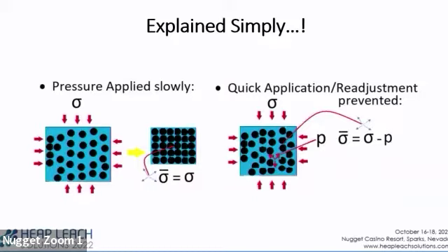The shear strength of a soil is the overburden effective stress, or the confining effective stress, times the tangent of the friction angle. The effective stress is the total stress minus the pore pressure. So as you pressurize the water, your shear strength goes down. And if you pressurize it enough, your shear strength goes to zero, and that poor sweet mom in the Western gets swallowed by earth. So we don't actually see full liquefaction like that very often.